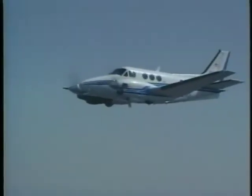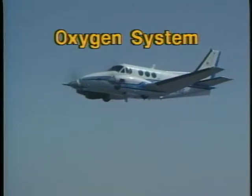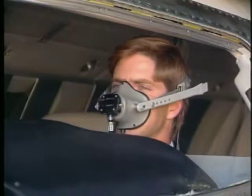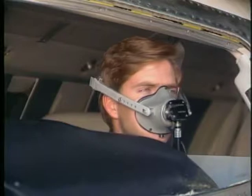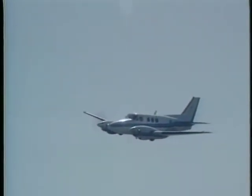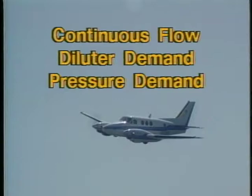Another environmental control system commonly found on high-performance aircraft is an oxygen system. Federal aviation regulations require the use of supplemental oxygen above certain altitudes in order to compensate for the body's inability to get enough oxygen through normal respiration. There are three types of oxygen systems: continuous flow, diluter demand, and pressure demand.